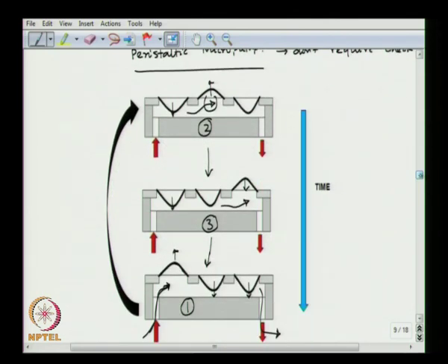One issue with the peristaltic micropump is that when it is operational, it is fine, the liquid goes from the inlet to the outlet. However, in situations where the micropump is idle and you have already pumped some fluid from inlet to outlet to a high pressure source, if the micropump is not operational, there is a possibility of backflow. To prevent that, we would need one directional check valve upstream.